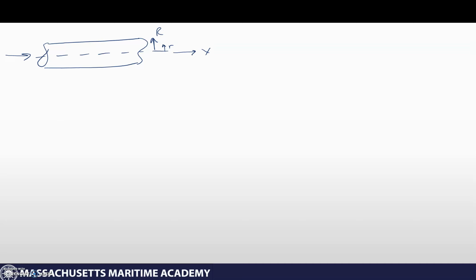And let's look at a small fluid element that we can do some differential equations work on. In that small little element, on the back side I have some pressure pushing it. On the front side, I have some pressure minus delta loss in front of it. We will call the length of our element lowercase l. And as I put over here, the radius will be r, and it will have some shear stress pulling back on it. So let's balance out the forces pushing on this element.